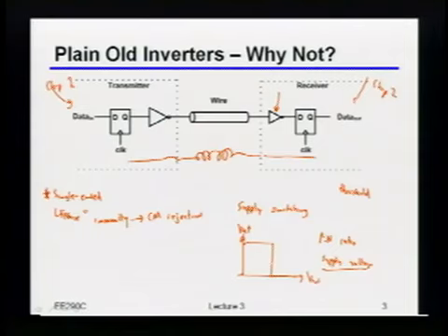So now, even worse than that, what's particularly bad about this kind of transmitter, from the standpoint of actually getting the inverter on the other side to receive what you think is a 1 and what you think is a 0? You'll have a supply drop, and there'll be IR drop through it. Okay, so you will have some IR drop. Let's assume that I do a good job, I know how to build the backplane, and I actually even make that magically pretty low. There's actually even a more nasty issue.